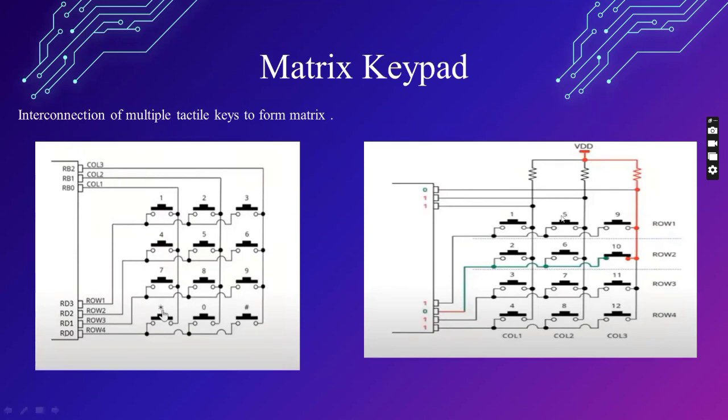To detect a key press, normally the corresponding row is 0. Then when the key is pressed, it makes the corresponding column to be 0, which helps us to detect the key pressed. And through this, we were able to construct our matrix keypad function, which aided us also later in our project implementation.